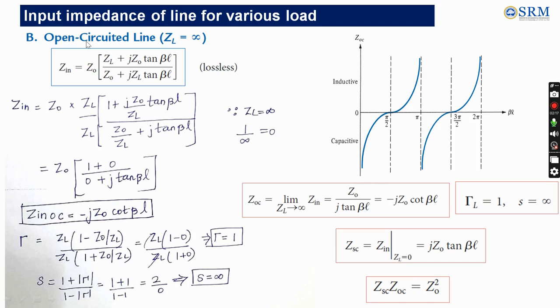Now let us find the input impedance of a line for the open-circuited condition, that is, when the load is infinite impedance. In that case we can't directly apply ZL as infinity, which makes the entire expression infinity.